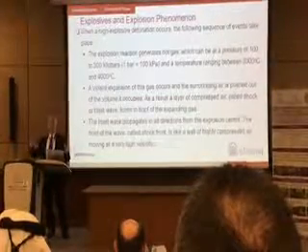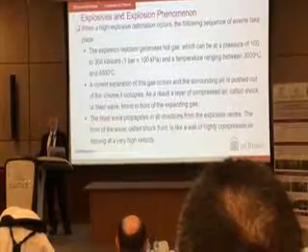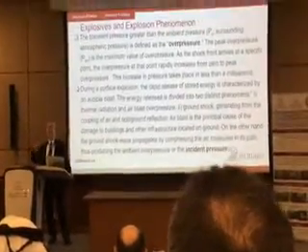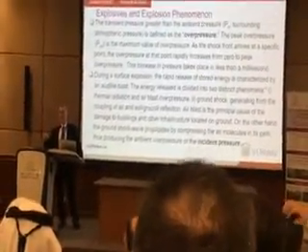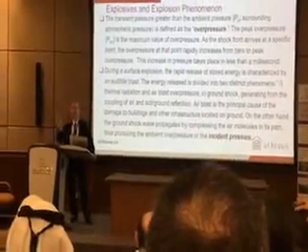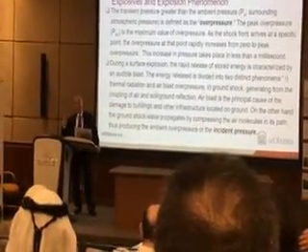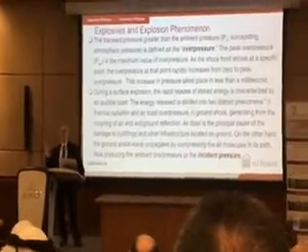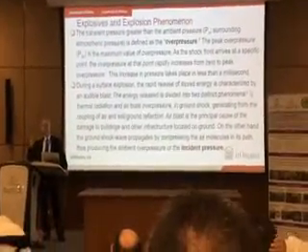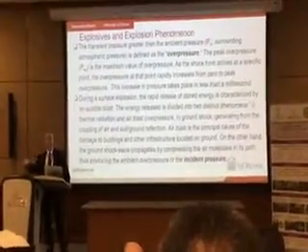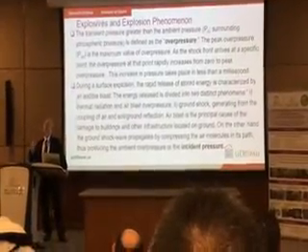And this violent explosion starts causing a shock wave. This shock wave is referred to as overpressure. Anything that is higher than atmospheric pressure in blast engineering is referred to as overpressure. But those overpressures that reflect from the ground are called incident pressure.